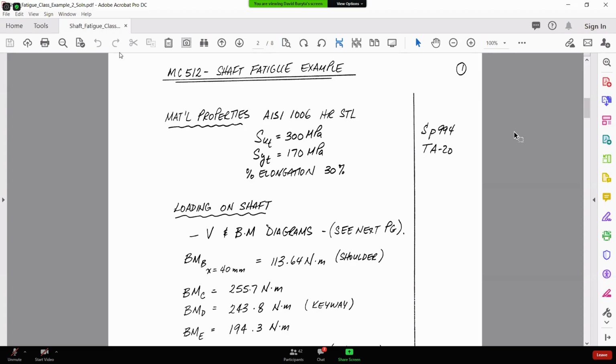let's say that in this particular case, it's hot rolled, and you wrote down the UTS as being 330 and the yield strength being 280, which is really the cold drawn, the CD, cold drawn material properties. If you don't tell me where you got those numbers, I can't give you part marks because I don't know where you got it from. But if I know where you got it from, I can look at the table and say, oh okay, you just made a simple mistake by looking at the incorrect row.